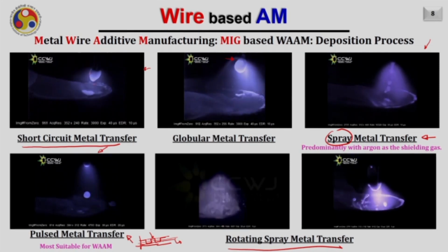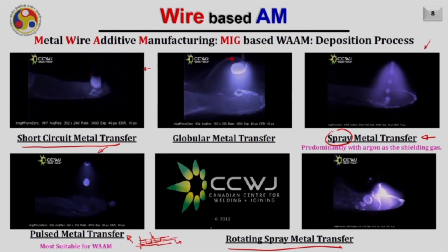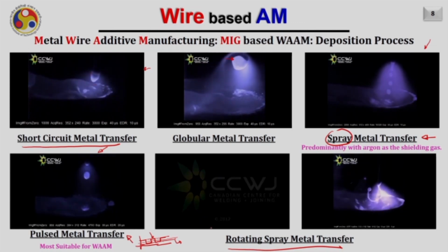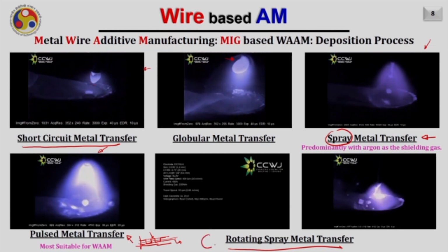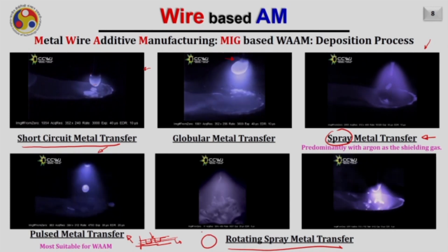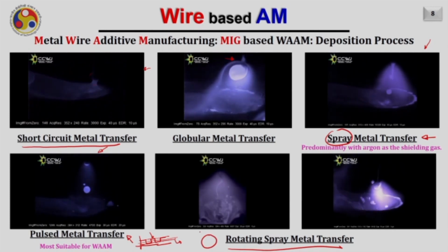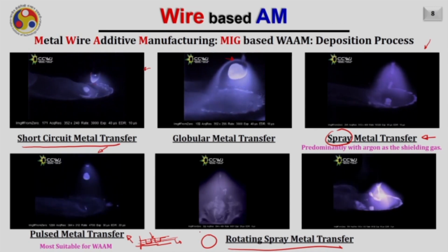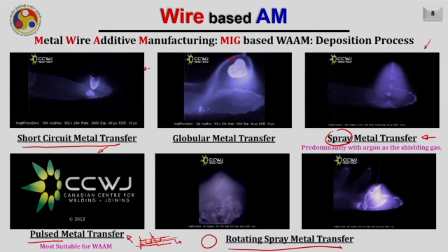In such cases, with the same current, the penetration reduces, but at the same time the width of the bead deposited increases drastically.